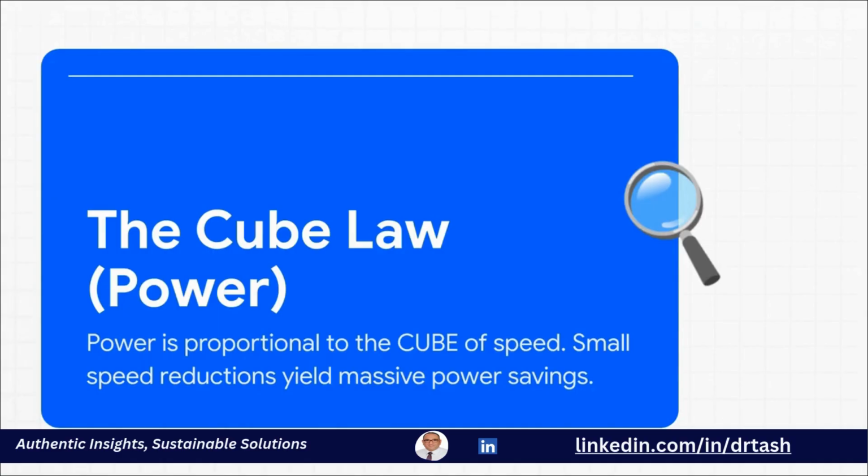And this right here, this is where the mind-blowing savings are. The cube law. Power is proportional to the cube of the speed. This exponential relationship is the magic behind why variable speed drives, or VSDs, are so incredibly effective. Think about it. A small 20% reduction in speed doesn't just cut energy used by 20%, it absolutely slashes it by nearly 50%. This is, without a doubt, the most powerful law in our entire toolkit.